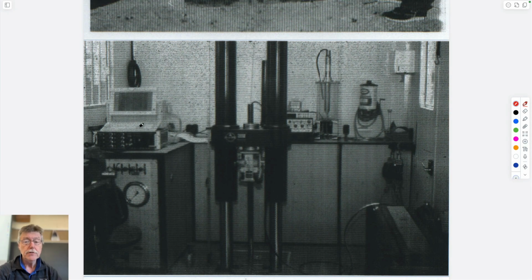Quite an old picture. It's an old computer. And then here, this is the cable that's measuring the end bearing stress, the sleeve friction from load cells, and the pore pressures from a transducer, and it transmits it up to the surface. And actually it's already pre-wound. It goes through a whole bunch of these typically 3-foot or 5-foot rods, which you just add another one onto the top here.